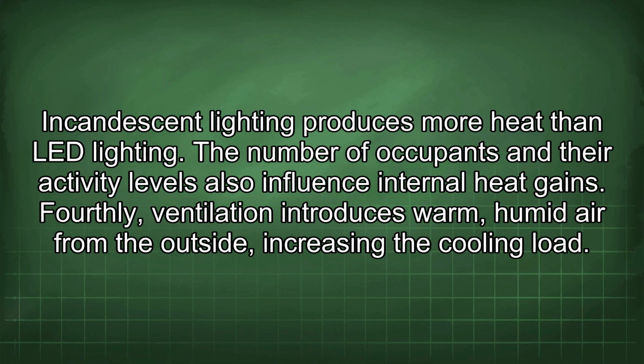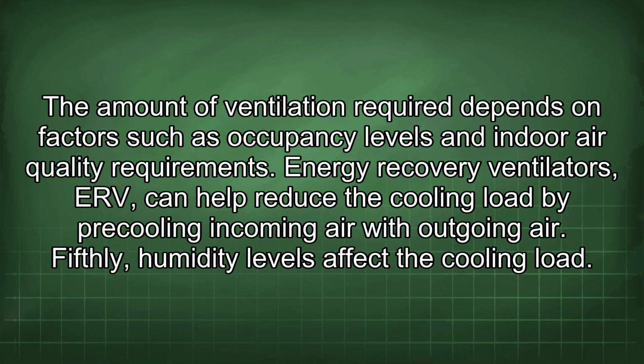Fourthly, ventilation introduces warm, humid air from the outside, increasing the cooling load. The amount of ventilation required depends on factors such as occupancy levels and indoor air quality requirements. Energy recovery ventilators, ERV, can help reduce the cooling load by pre-cooling incoming air with outgoing air.